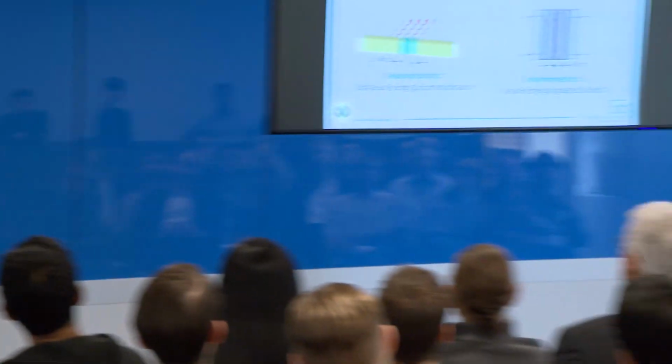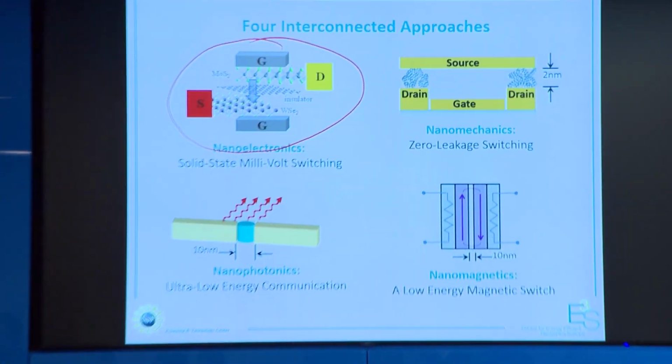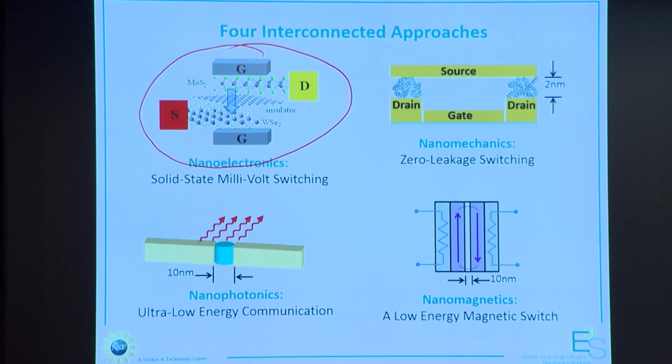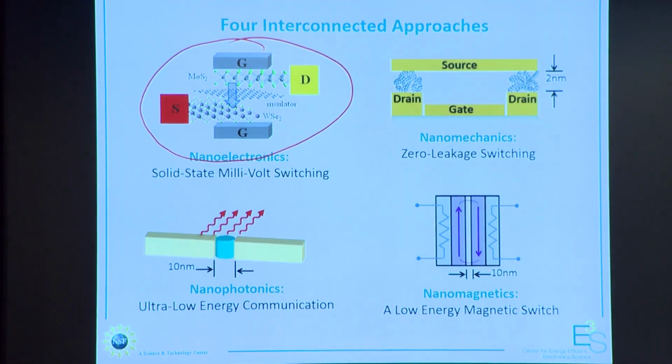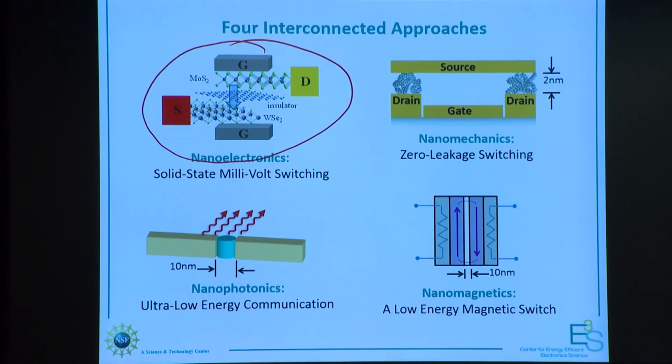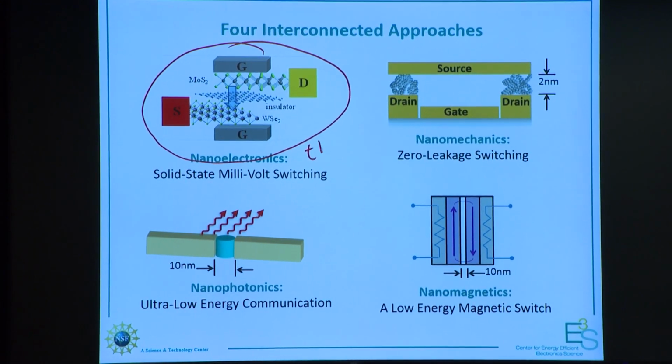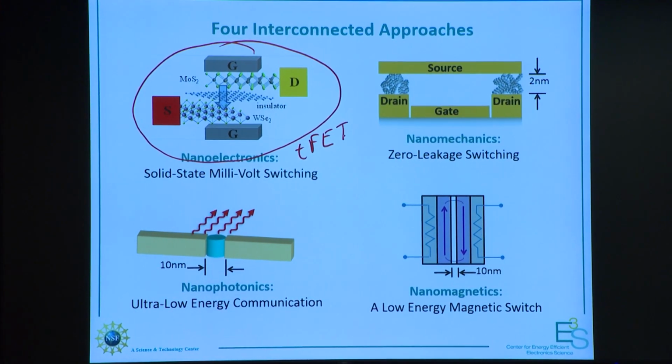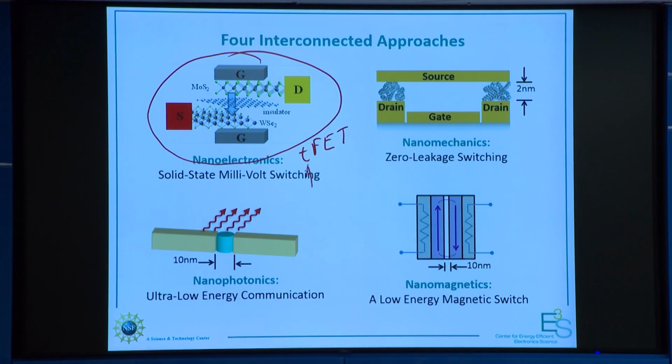And so what are some of the ideas? Well, there's an idea of maybe being able to do something with normal semiconductors. Wouldn't that be great? We just make a different device in semiconductors, and one of the devices that looks very promising is the Tunnel FET. Of course, on the nanoscale, everything becomes tunneling anyway. So if we do that, that would be terrific, because maybe we can just drop it in, replace the normal transistor, and it will be accepted right away. But you'll see soon that that's very hard. We're very far away from that.